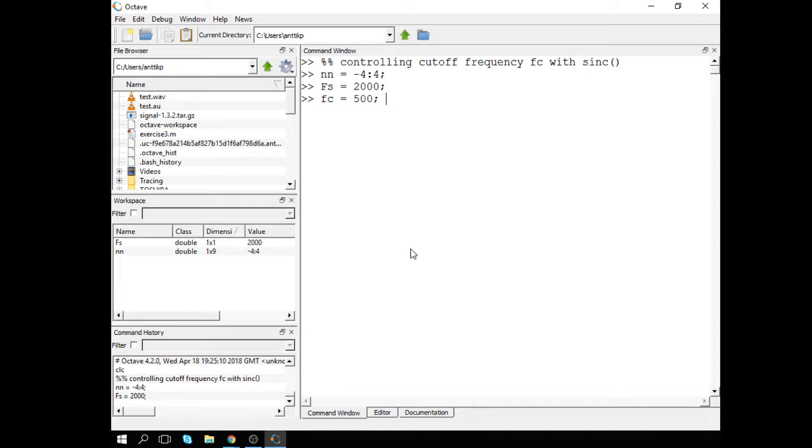So basically this will be a half band low pass filter. Right. So that's what I'm trying to do, or should I do something? So that's about 1 kilohertz. Hey, let me try to do this one. So that's roughly 350 hertz then. Yeah, I changed my mind. So this one is 350, just to make it look more like what I drew there.